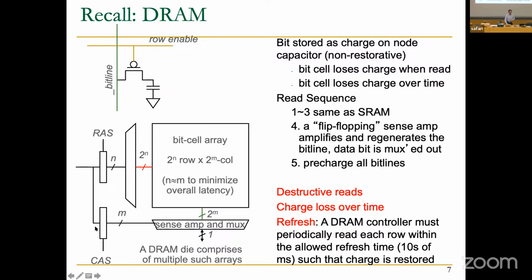And when appropriate, you supply the column address next and send the read command, coming out of the sense amplifiers there. And these are dictated by timing parameters specified by DRAM manufacturers today. And the reason why we supply the row address and column address in separate cycles, well, one of the major reasons is because this is a chip by itself, and it's limited by the number of pins that you can put. So if you want to supply the row address and column address in parallel, you need to double the number of bits that you need to use to supply address with.